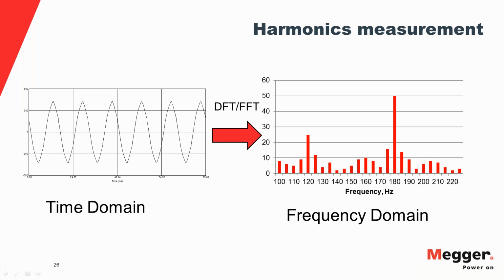So if you take those three 5 hertz bins around 180 hertz, you get a single 15 hertz band, and all the frequency components in this band, so 180 plus 7.5, 180 minus 7.5, would be grouped under the third harmonic.